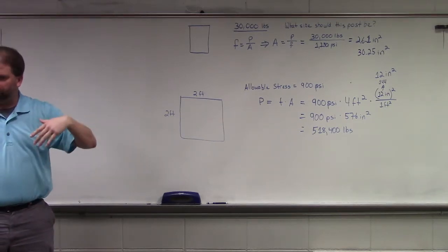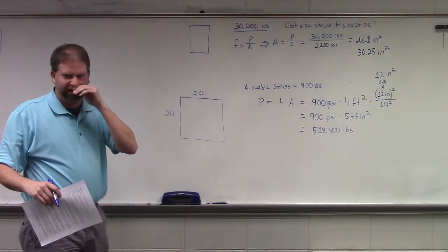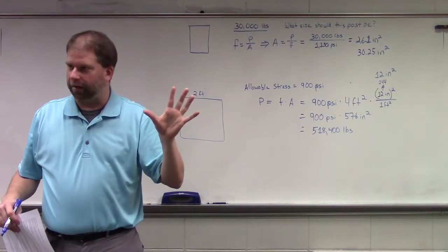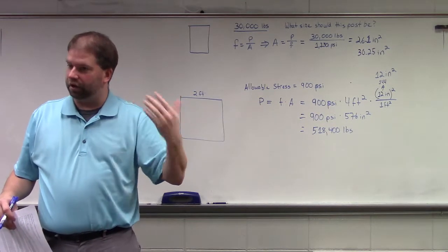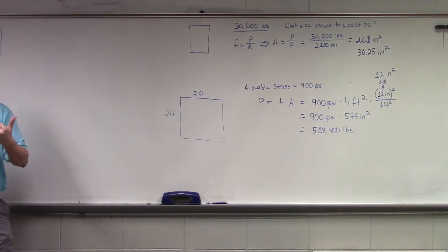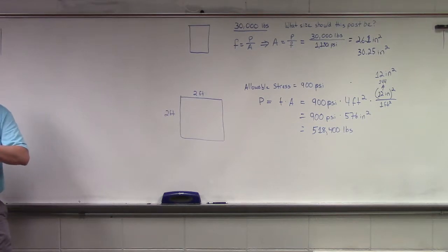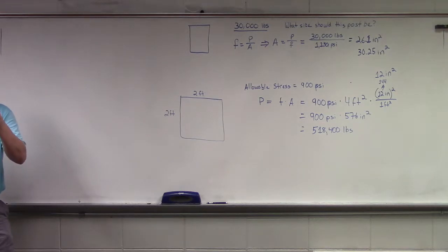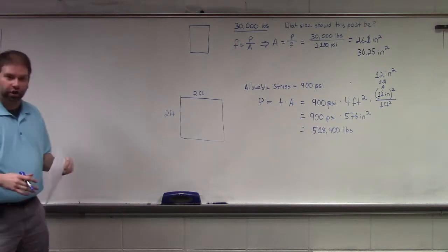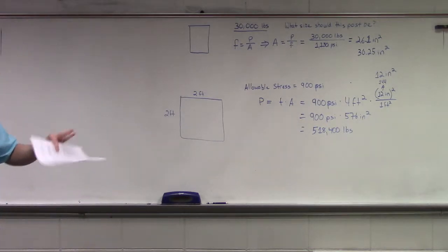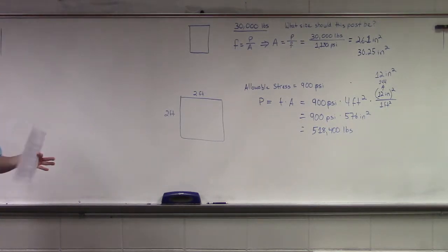So structural engineers come in. He's done analysis on the roof trusses. It can take the overall weight of this track. So we need to figure out, the engineers come to us and say, "Hey, if you put in 7/8 inch rods, you're going to be good to go." Talk to the manufacturer, they're fine with building up the ends so that when they cut off those rods, you have that 7/8 inch effective diameter to carry the load. We want to make sure, once people start using this track, that it's not going to completely fall down onto the gym class below. That would make us look bad, right?